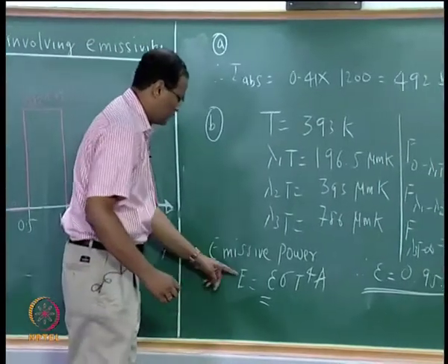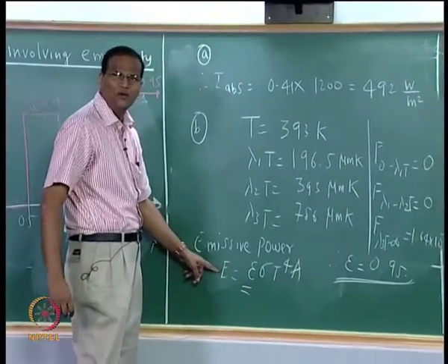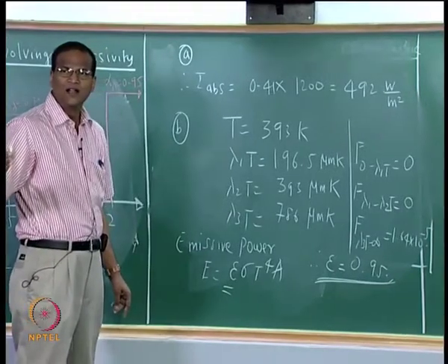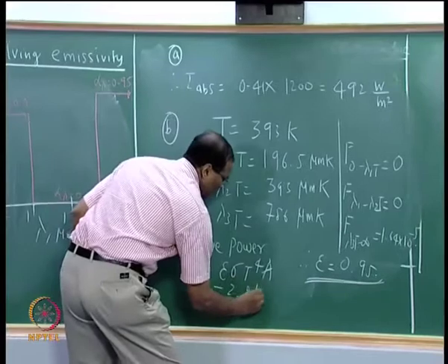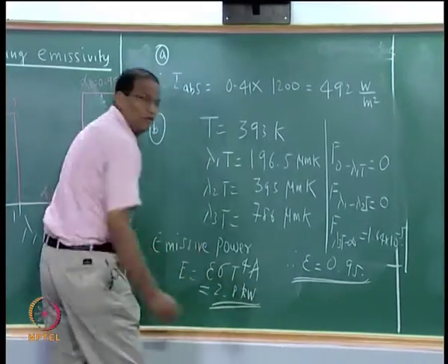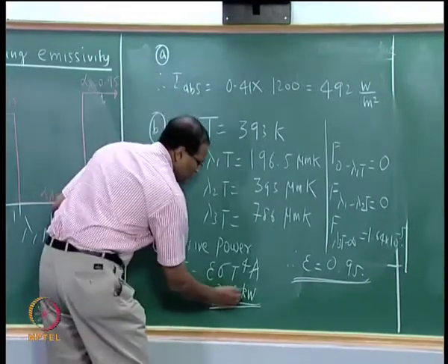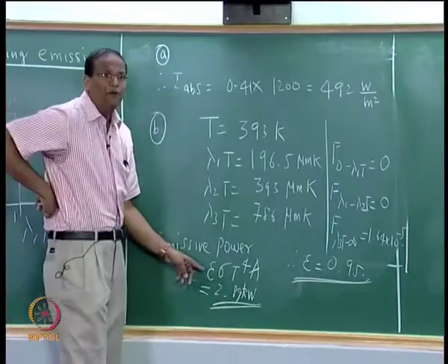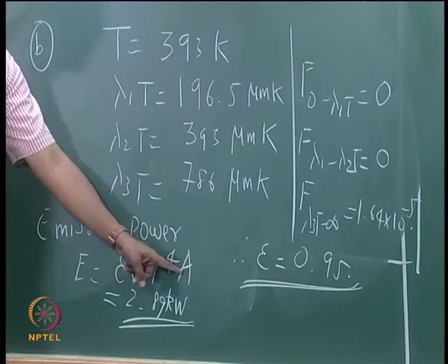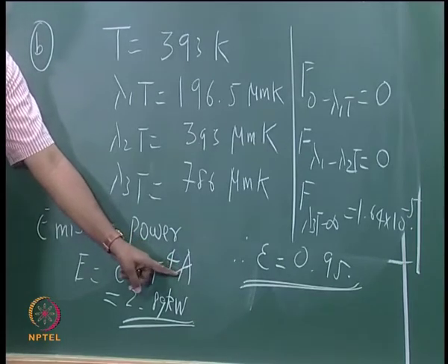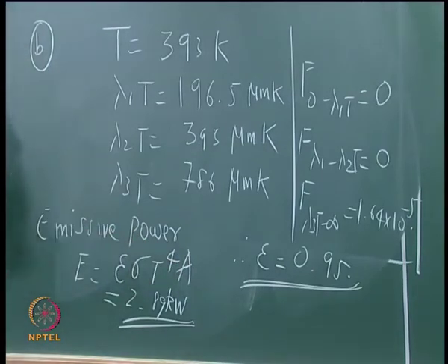Then I will put 2891.3. Should I put E or Q? E, okay. 2891.0, 2.8 kilowatts. 2.89 kilowatt. 2.89, okay. Some people who have not been following, or you are busy with doing your own stuff, I gave you the area in this problem, 1.5 by 1.5. You can put the A and convert the watts per meter square to watts. Keep it like that. Okay.